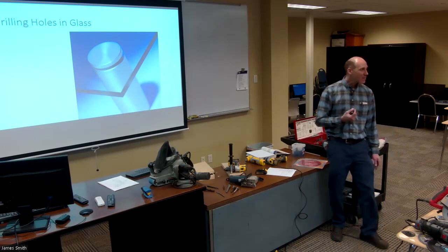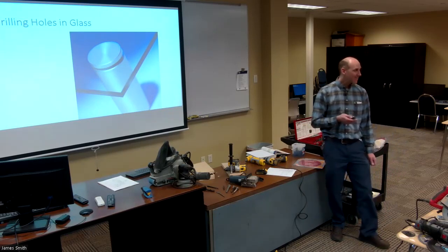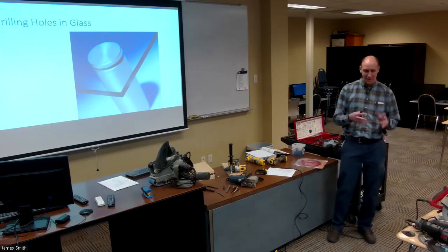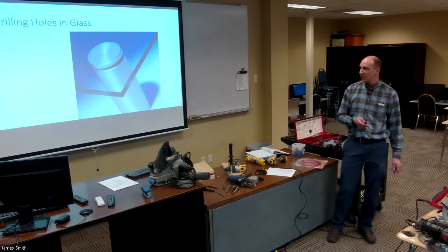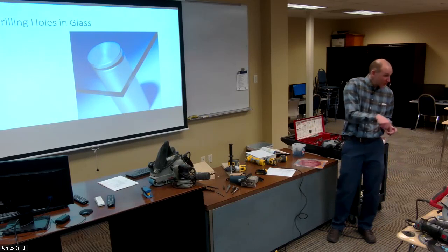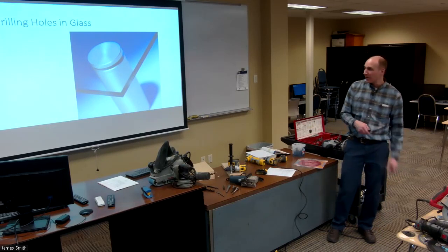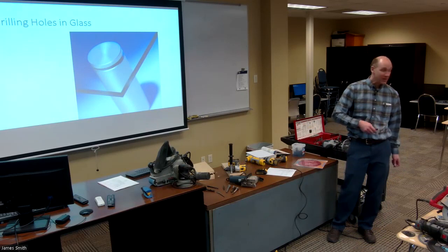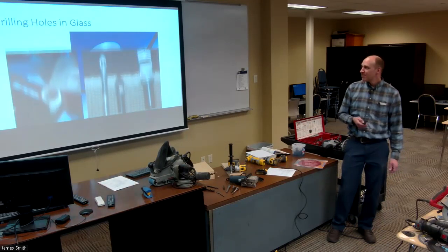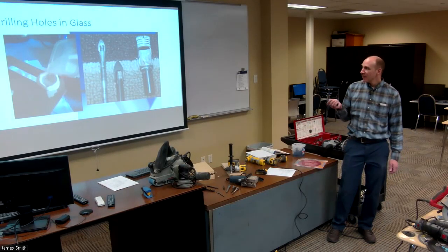And even with diamond, you've got to keep it cool. You can't shock the glass. Heat is just your enemy. Ideally, you'd have one of those little water jet tables. You could use a jet of water with a little bit of abrasive mixed in. They also have these little carbide tools that are designed for drilling glass.